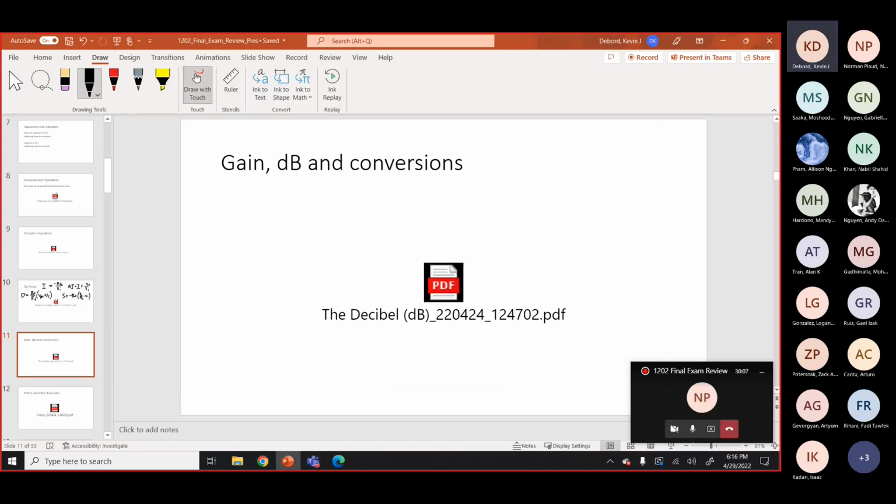Okay, so gain decibels conversion. Volts per volt to decibels is 20 log base 10, but that's implied when you say log, and then your gain, right? Okay, easy enough. So what are we going to do to convert back to gain from our decibel value? You can do a lot of other fun stuff that I'm sure Professor Kogan has told us to do, but what's a very simple method that we learned in calculus? Very simple method. Converting: 10 to the power of the answer divided by 20.